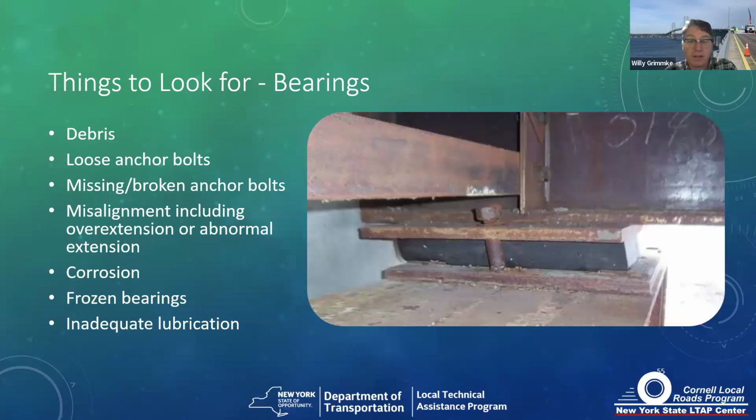Moving down, bearings. How are your bearings behaving? Are the anchor bolts like they're supposed to be? Is it overextended? Is it corroded? Is it frozen? Does it need to be lubricated?